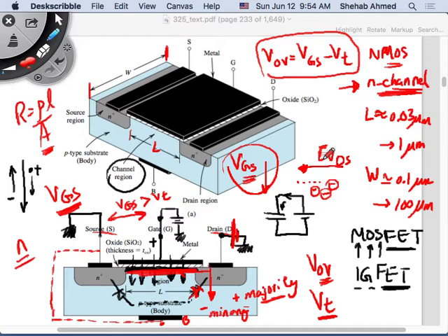What will this electric field do to electrons? Electric field will cause drift of electrons. You have a bunch of electrons here that were created due to the gate-to-source voltage, which created this electric field that gave me the depletion layer and brought up these negatively charged free electrons. These free electrons I'm now exposing to another electric field because I applied another voltage here. Initially, I didn't have this voltage. I was connecting this to ground. And then I added a voltage here.